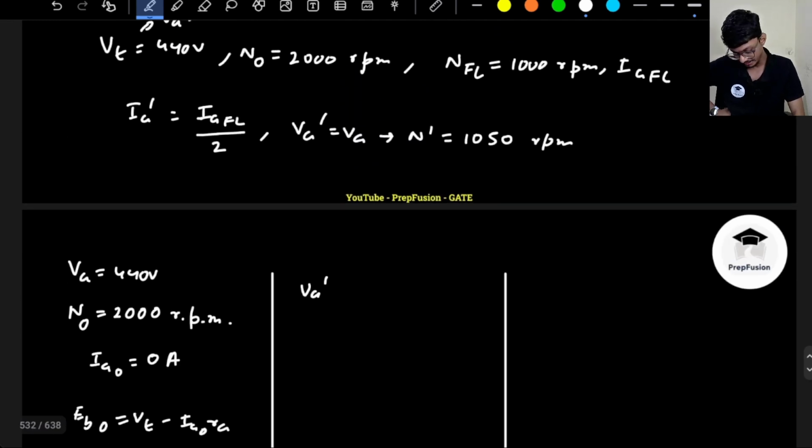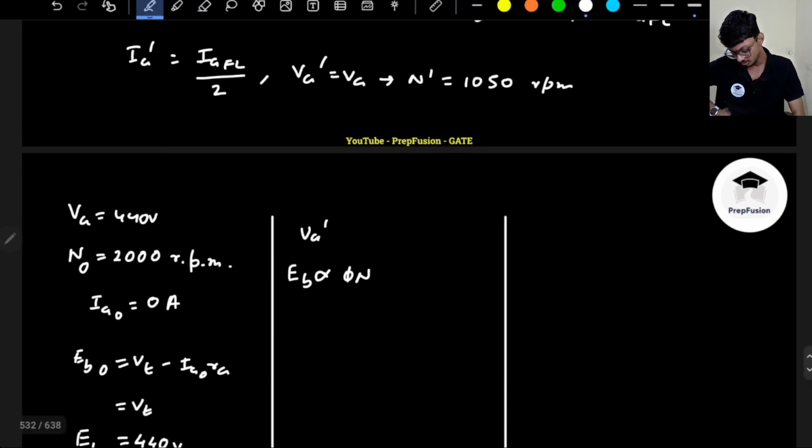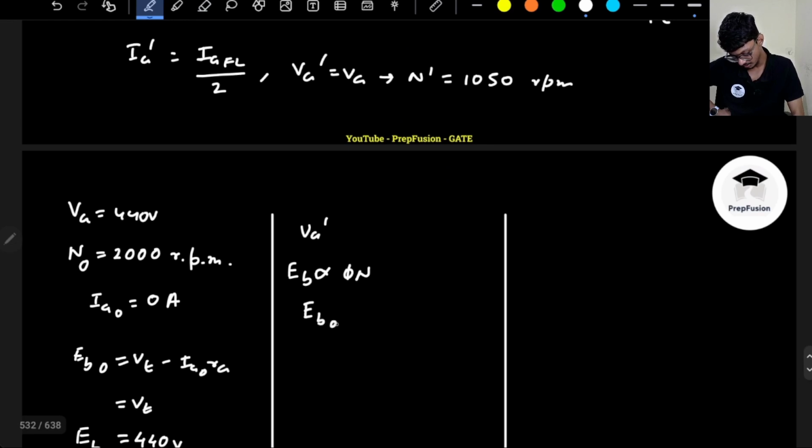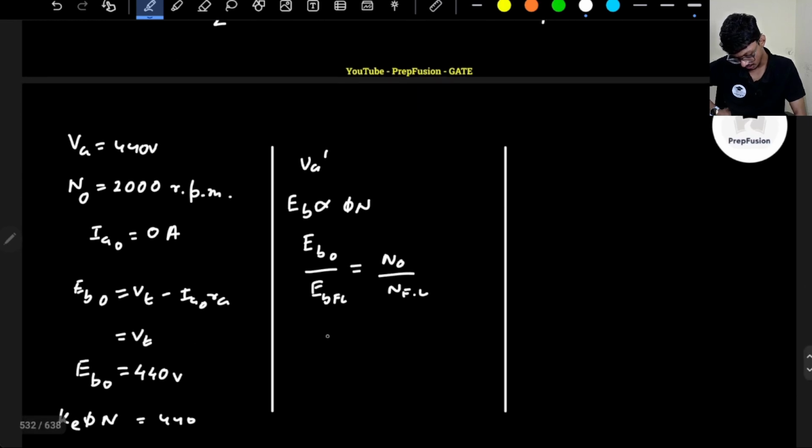Yes, right? Because my Eb is proportional to flux and speed. So Eb naught by EbFL will be equal to N naught divided by NFL, because the flux does not change. So what will happen?